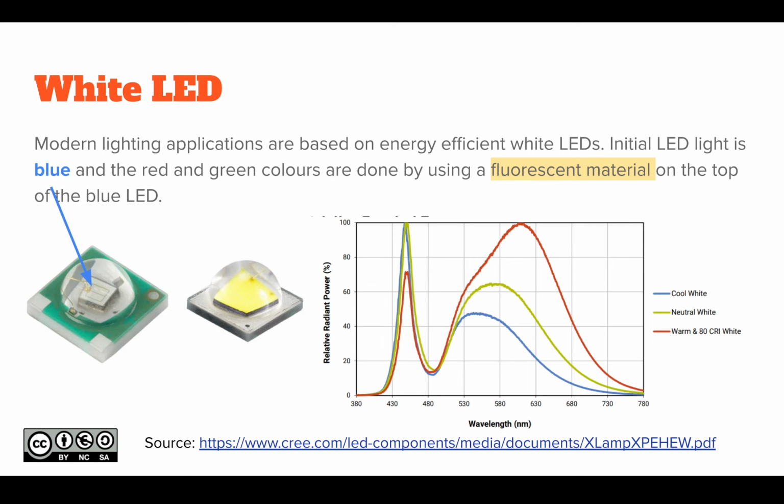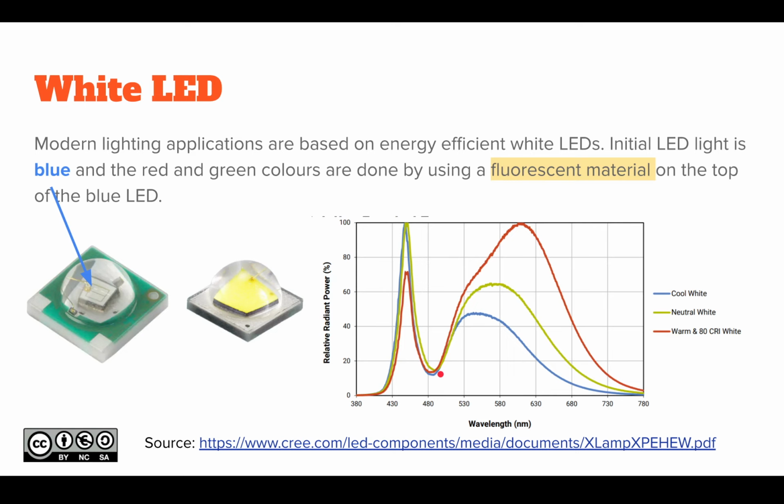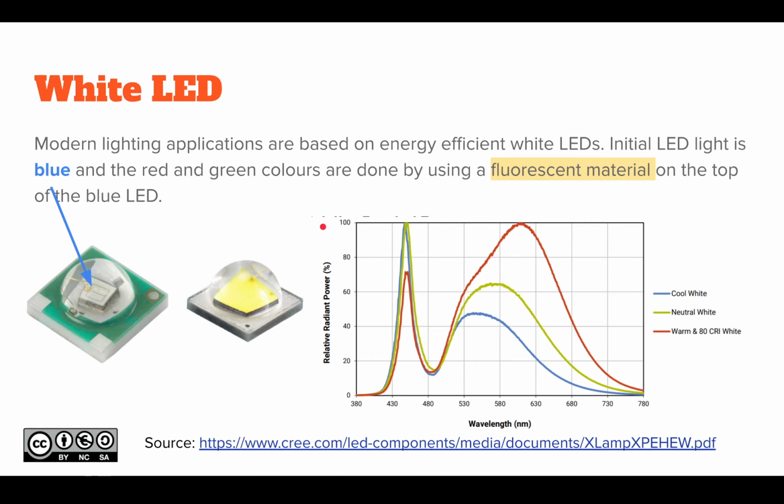And then I tried that green screen on my video equipment and noticed, no, it's not green. None of my cameras are actually seeing much green. It was more like a gray. That's because the white LED spectrum doesn't have much green at all. So if you make a green screen, use green LEDs to light it. That's on my shopping list next. But anyway, white LED, that's how it works, for example, in your flashlight.